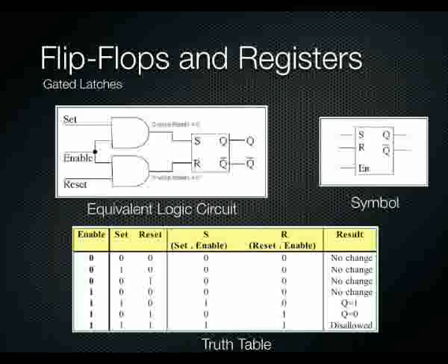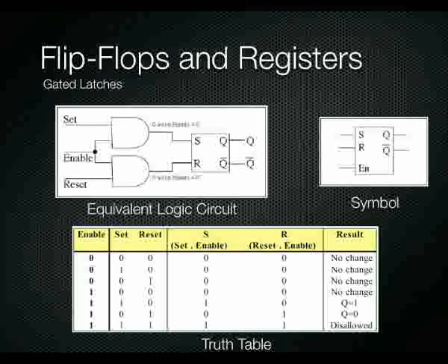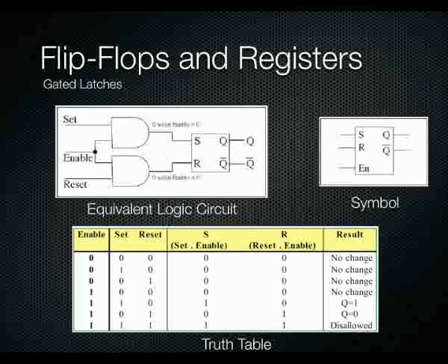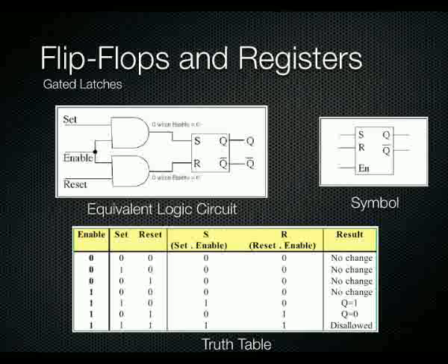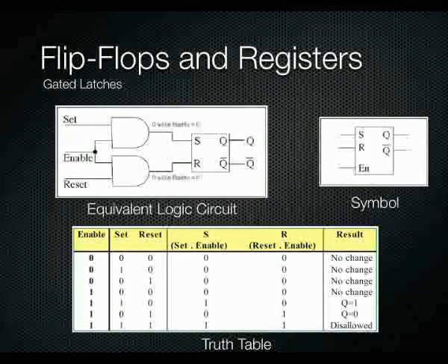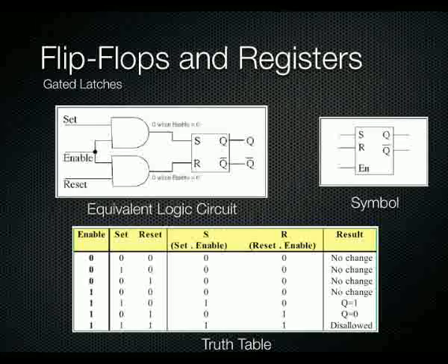But of course, an RS latch is a very simple latch. You need to take that to a few levels higher. So with gated latches, you can effectively put an enable line on there. Therefore, if you want to have numerous latches and only use one particular latch at a time, you need to be able to enable a particular latch at one point in time. So we have gated latches.